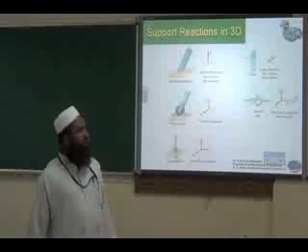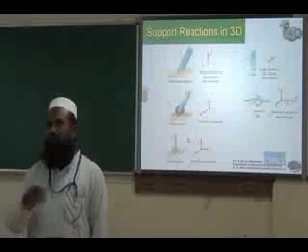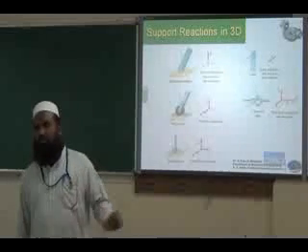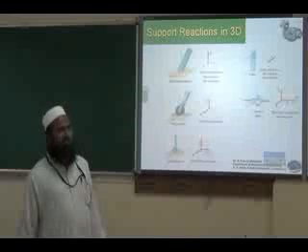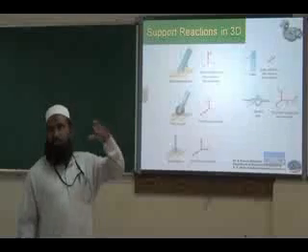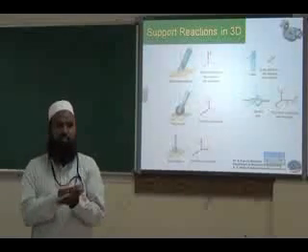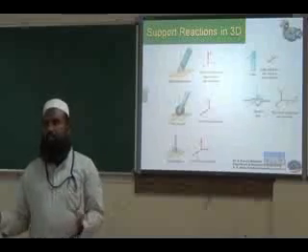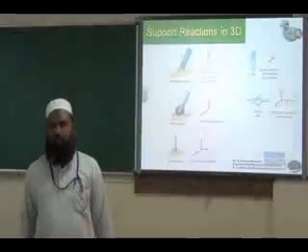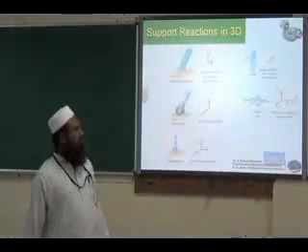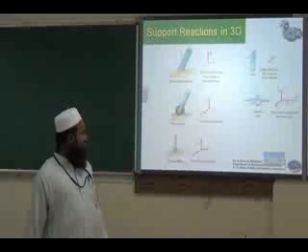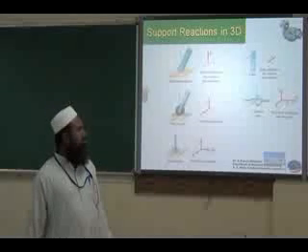Third case, you have a ball and socket joint. The ball and socket joint can rotate in any direction, but it cannot move in any direction. So no translation means you will have three forces. Here only one translation is arrested, the translation in z direction. Smooth surface, so it can slide in x direction, it can slide in y direction. It cannot slide in z direction because of a support at the bottom. So you have only one force. Here you have two forces because two movements are arrested. You have three reactive forces because the three movements are arrested.